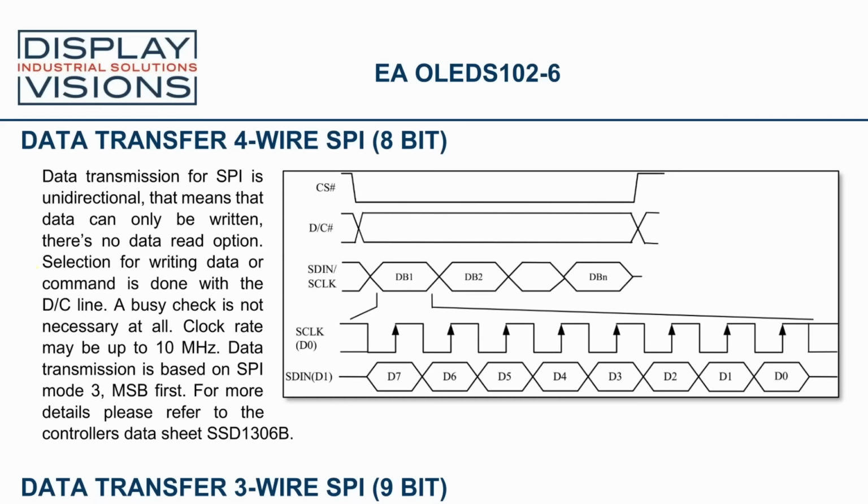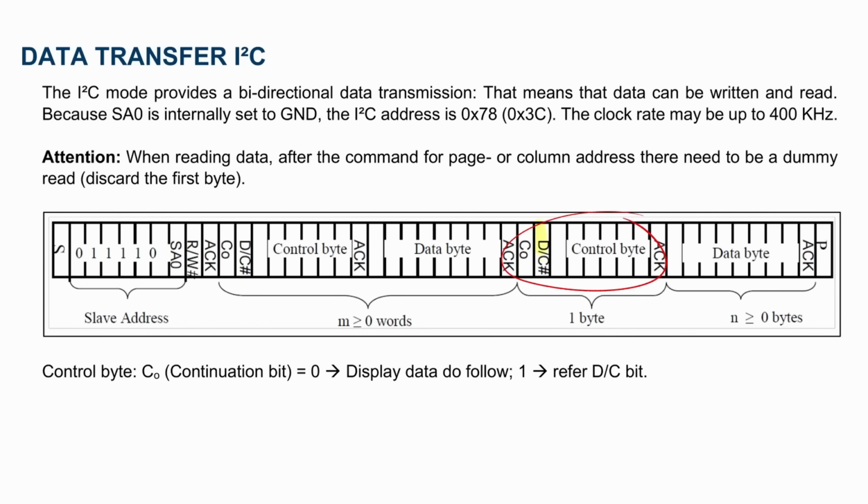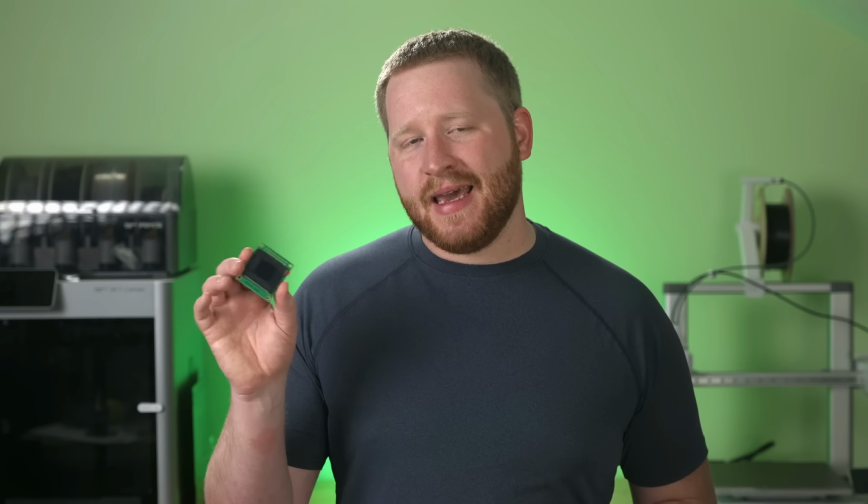Once you've established a frame buffer, the next step is getting that data to the display. First, you generally need to tell the display that you're about to send it frame data. Sometimes this is done with a discrete input signal, other times there's a command sent over the interface, as is the case with this display. It is also sometimes necessary to set the starting point for the data. Basically, you're setting the pointer for the first pixel you want to fill, and the display will increment from there.